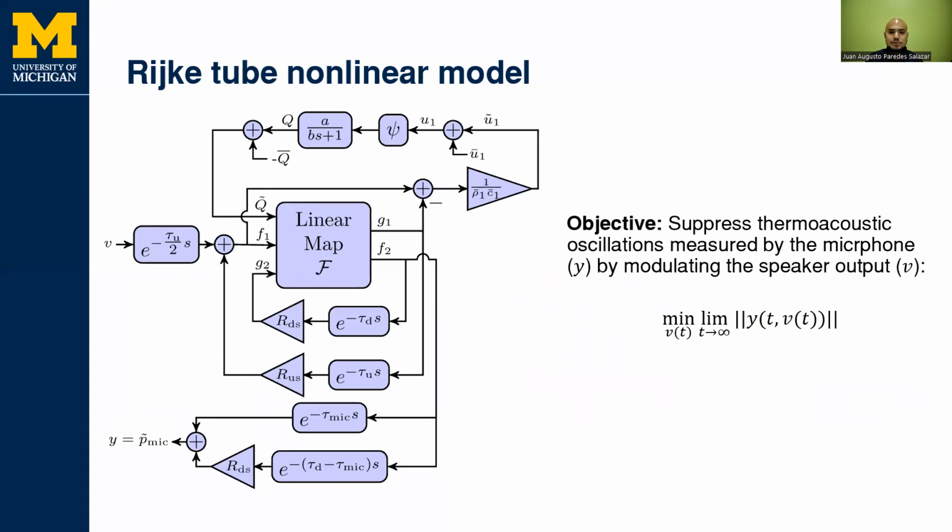The objective in this case will be to suppress the thermoacoustic oscillations measured by the microphone by modulating the speaker output, which is formalized by the formula on the screen.